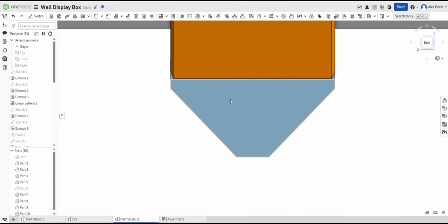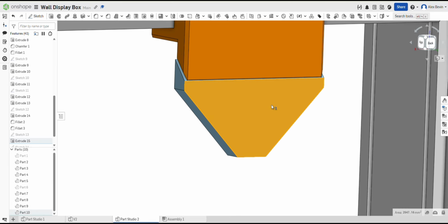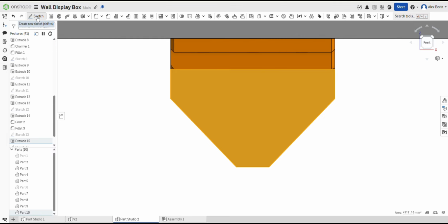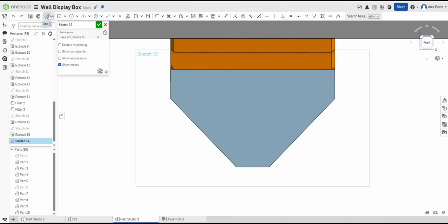This is the point where it's easy to cut the wrong part. Make sure the cut is removing from the bottom cleat, not the top plate. If you're not sure, hide the top plate for a second, do the cut, then unhide. Press OK. Nice, clash gone.